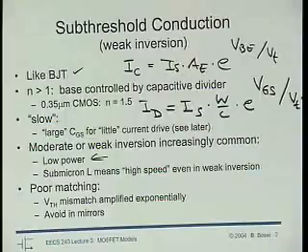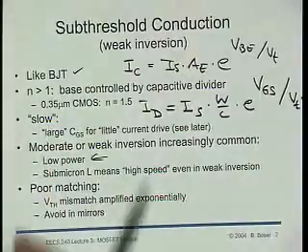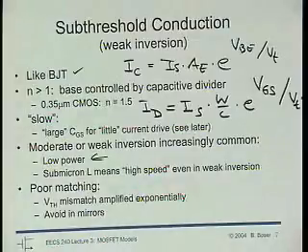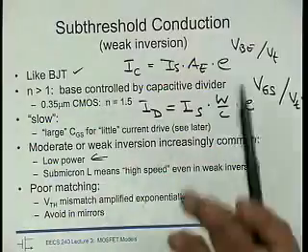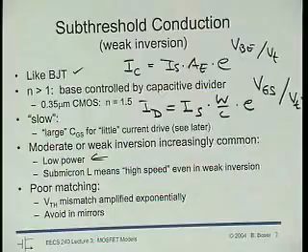And so invariably, we need only a few microamps to run our amplifier at 100 megahertz. Well, and then the device is in weak inversion, right? So when I took the equivalent of this course, well, unless you wanted to go at kilohertz speed, weak inversion wasn't for you. Well, now often we run a device at 100 megahertz, and it's almost in weak inversion.